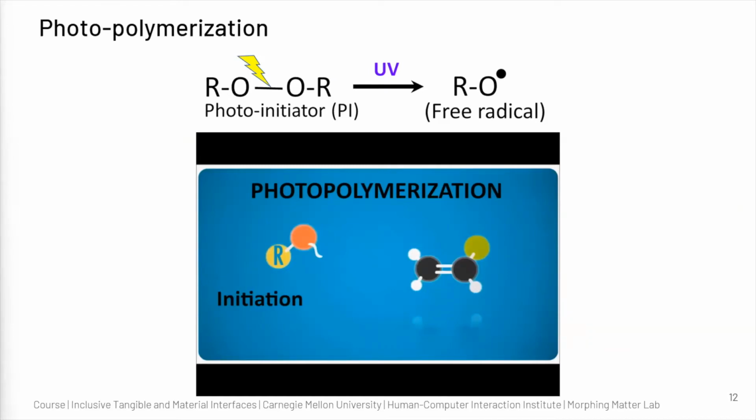When you talk about a photoresist, it comprises three things. The first one is called monomers. The second one is called oligomer or crosslinker. And the third one is called a photoinitiator. I call the photoinitiator the heart of this process, because if you don't have a photoinitiator, the resin will not undergo photopolymerization. So let's take an example.